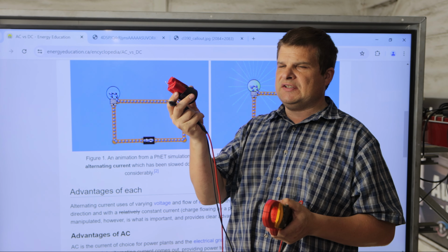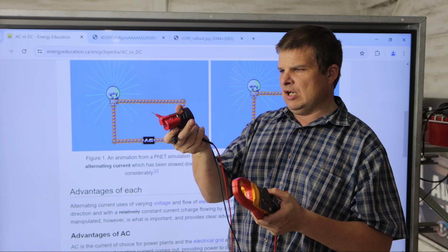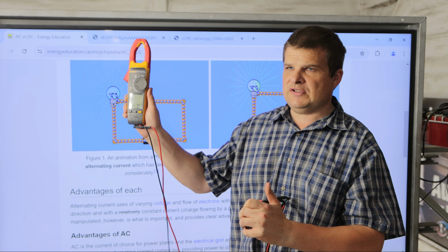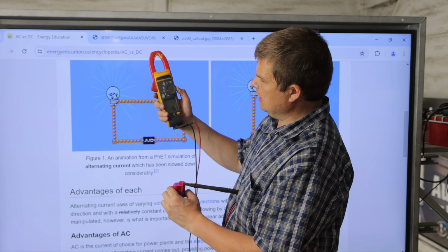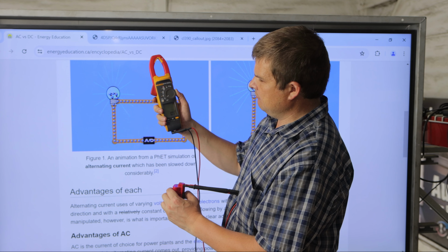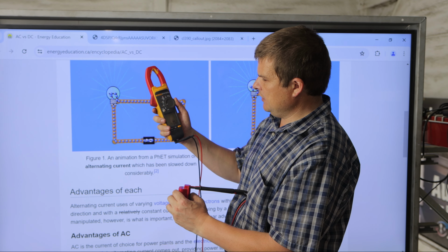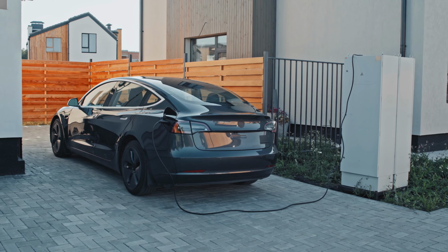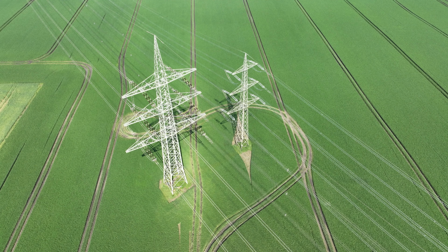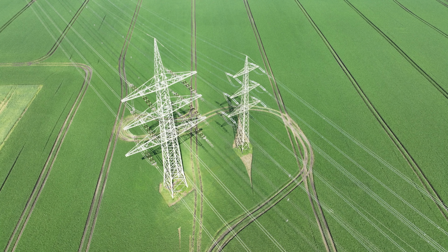So here I'll take a DC measurement with a Milwaukee battery. So if you can see here, we got 7.5 volts DC, and I got minus 7.5 volts. If I put it to AC, there's nothing there. Back to DC, 7.5 volts. So when you're talking batteries, you're gonna need DC. When you're talking power for your house, it's almost always AC.